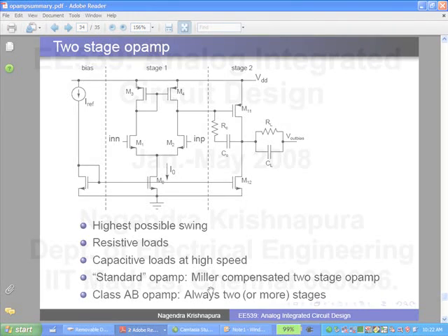You may need high DC gain in the application for the op-amp. Oh, because you can afford to have a second stage with a low gain. Well, the question was, what makes this op-amp so good for driving resistive loads? So you can make the second stage with a relatively low DC gain while it is driving a resistive load. But you can put all the burden of getting DC gain on the first stage. You can use a cascode stage, right? Using cascode in the first stage will improve the DC gain, but in the second stage it won't do anything for you.